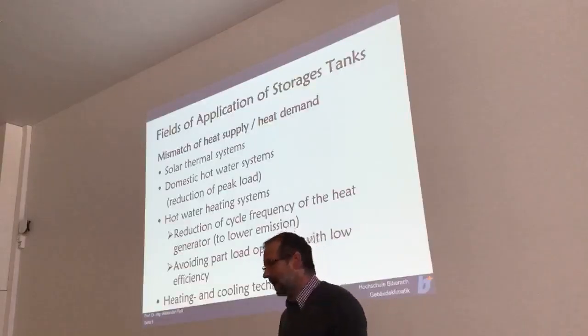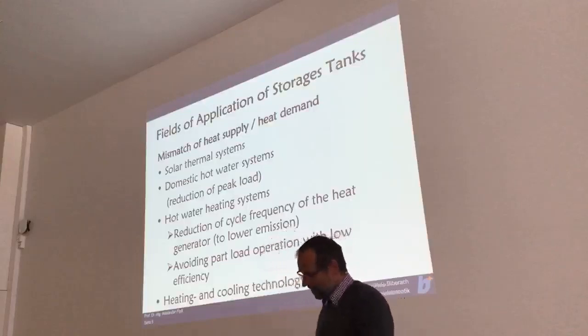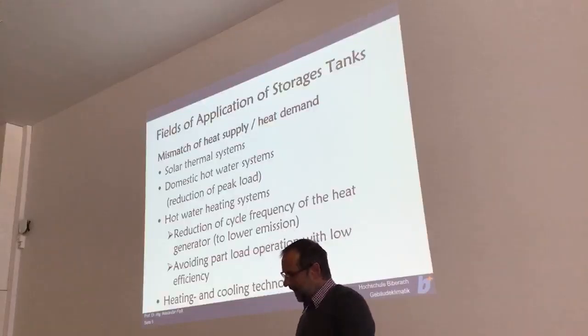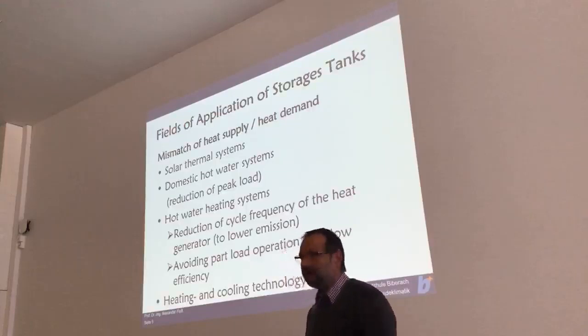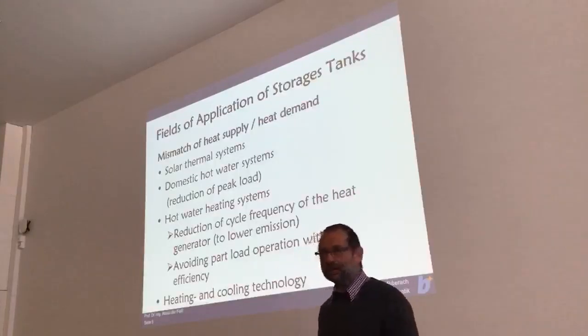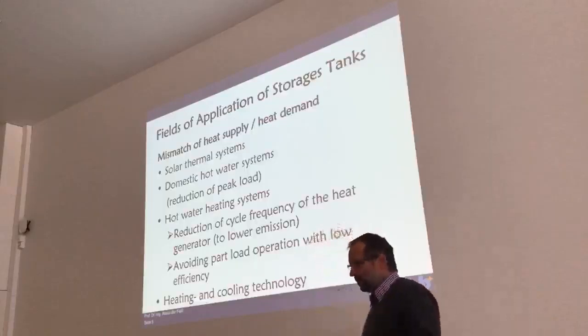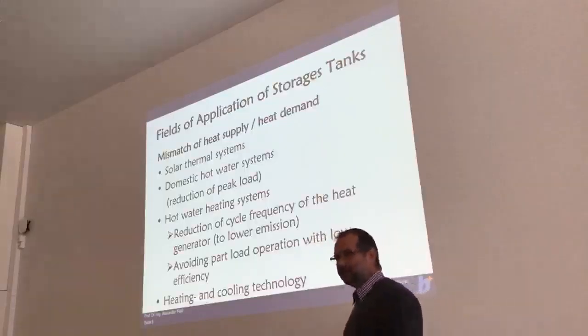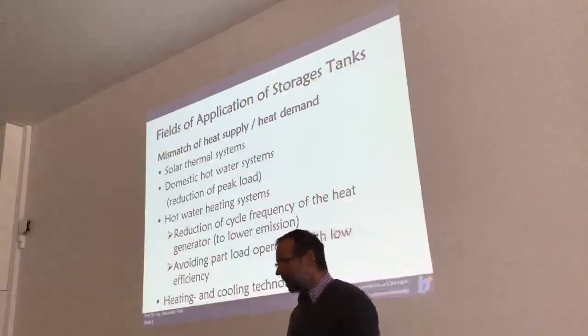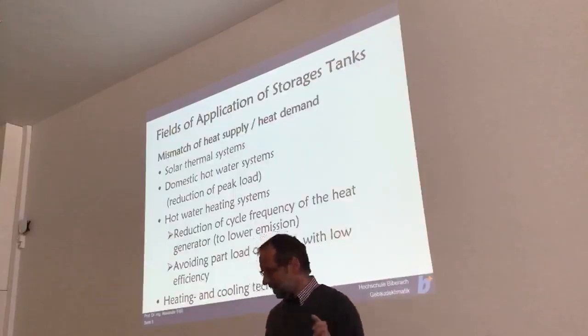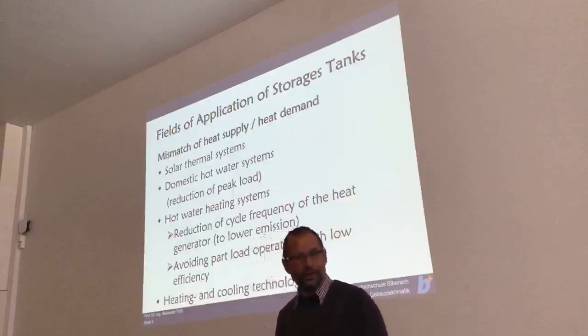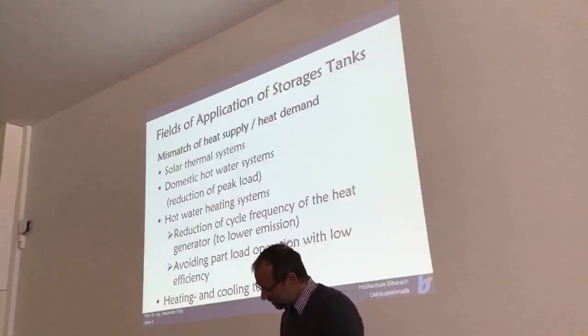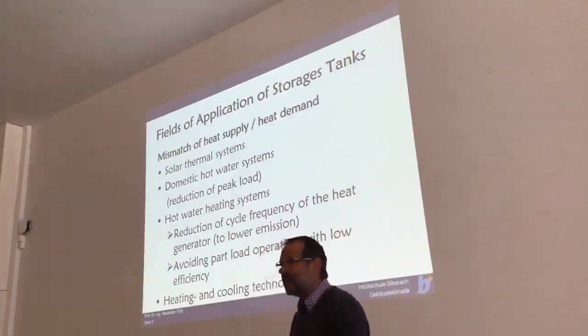That reduces lifetimes very much. Another thing is some of the heat generators have a lower efficiency under part load conditions. And so you should not run them under part load conditions because you lower the efficiency. You run them under nominal load conditions and just switch them on and off. And therefore you have to store the energy.